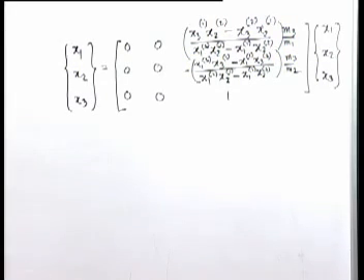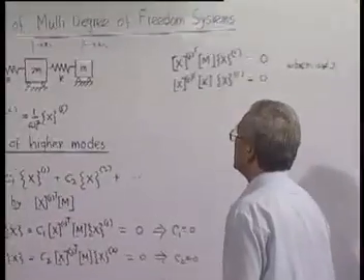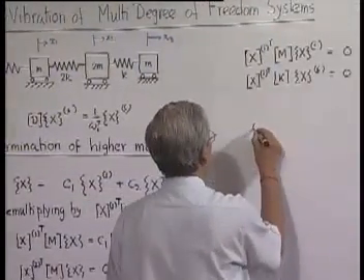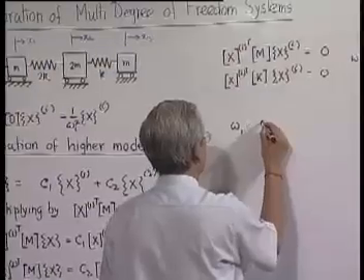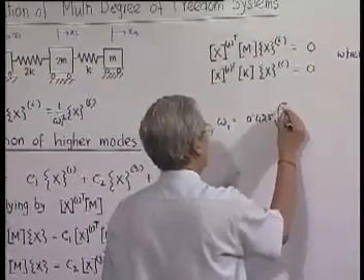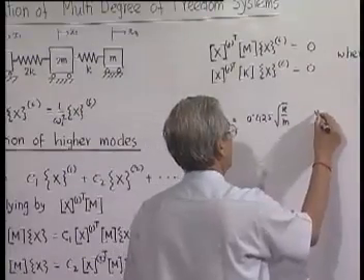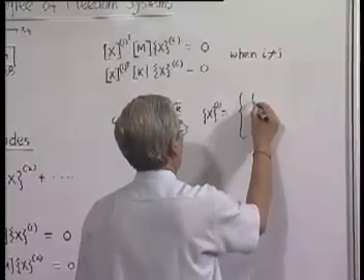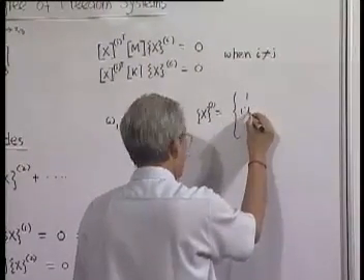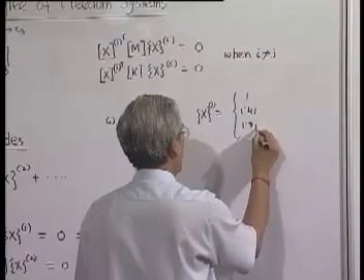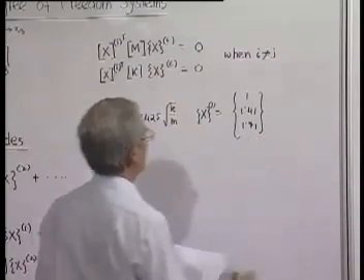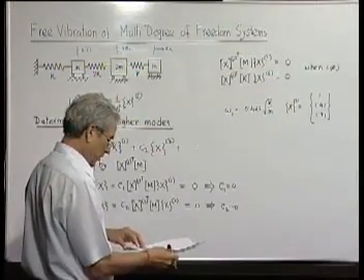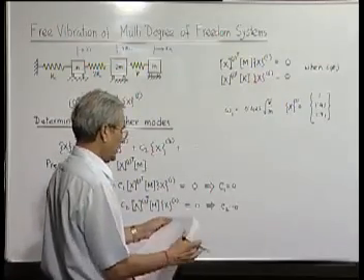To solve the same problem, because already the first mode has been solved, for which we know that your first mode omega 1 is 0.425 square root of k by m and x1 is 1, 1.71 or something, 71 or 72. This is solved. So now we should be able to figure out how much is going to be the second mode.